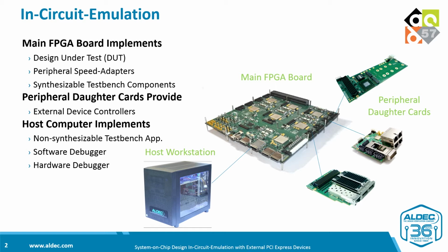There is one more component in this environment, the host workstation, which greatly facilitates test management and implementing non-synthesizable test bench application. This test bench application orchestrates the entire emulation process. The same host workstation can be also used to control software and hardware debugging.